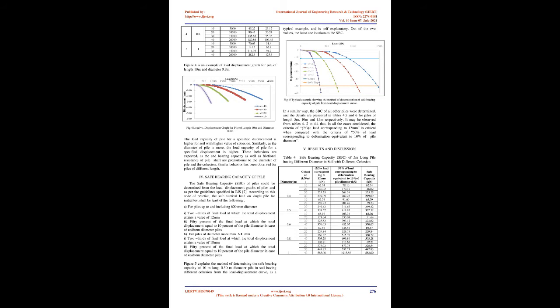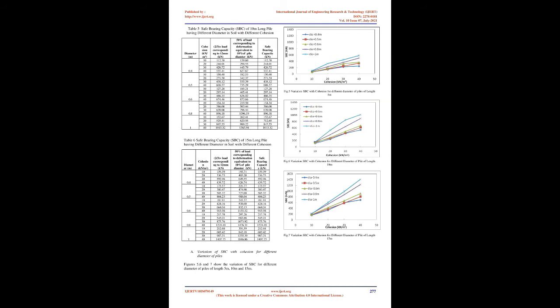A 3D numerical model was developed to simulate the single pile in clay soil. As the first step of the modeling process, the geometry of the single pile and the soil block were defined. The soil volume was modeled as a 10-noded tetrahedral element and has a depth twice the length of the pile in the soil model. The soft clay was modeled in the undrained condition.